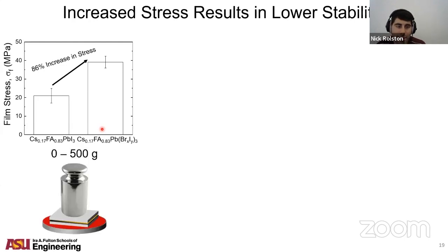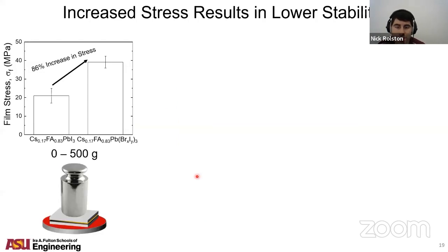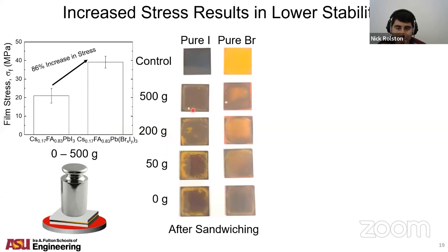We actually tried to enhance this interdiffusion process by putting different weights on top of the stack. In all cases here, this is after our annealing, 150 C for an hour or for 12 hours, and you can see on the left and on the right we have some phase mixtures.